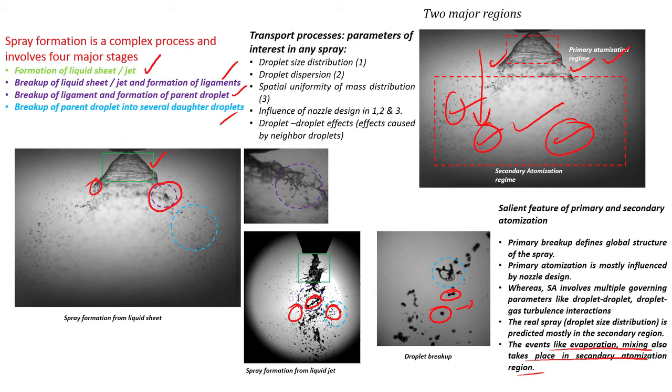So, these nice pictures show how the droplets break up, and they are not spherical. That is what we told, that they are like this or like that, all kinds of shapes, okay. Obviously, all these shapes are unstable, because as you know, the droplet or liquid blob always tries to be spherical no matter what. So, in that process it starts to split, and generates smaller and smaller droplets.